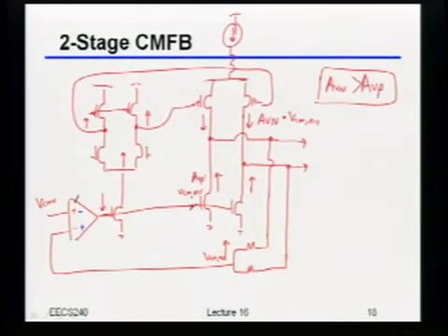So by doing something like this, by the way, if I really did add that current source in, which way would I choose these? Red or blue? Blue, right? Because I just got rid of that whole negative feedback loop from the other side. Okay?